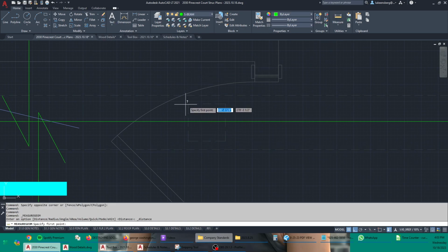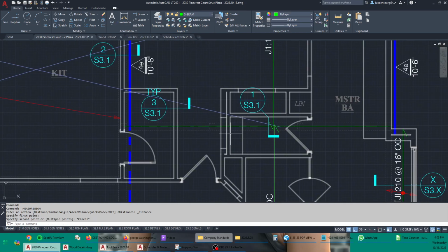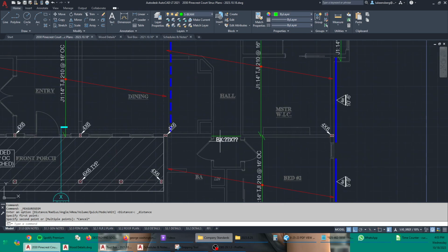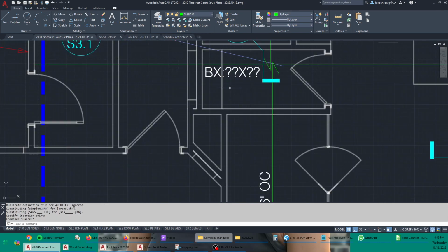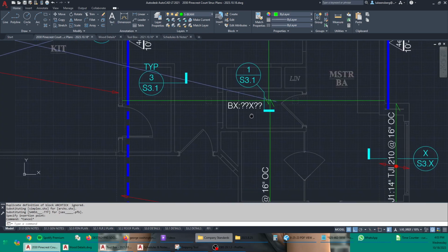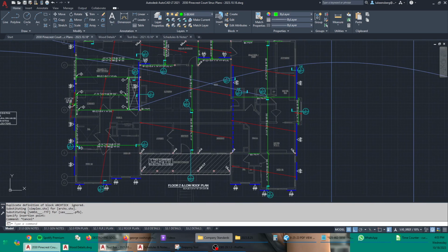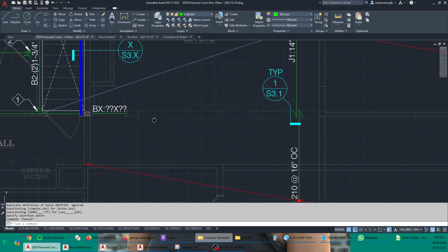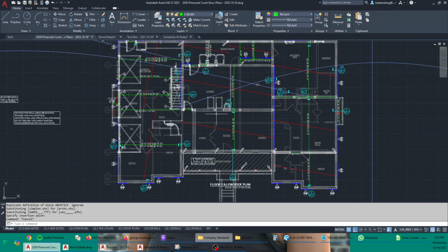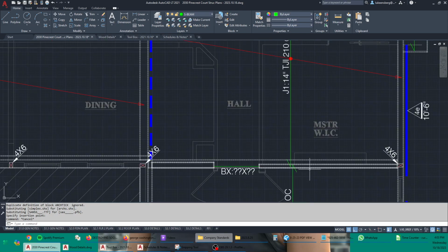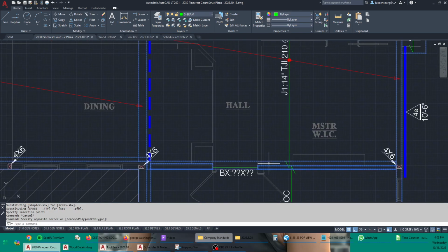The architect has done a pretty good job of thinking this building out. 5.5 by 5.5. So he's seeing these as 6x6 posts, which should be just fine. That should be more than enough capacity. There's my beam label. Question mark means I haven't designed it yet. Looks like we're going to have a similar case over in this area. I'll have to look around for other cases like that. Maybe this one too. Let's go back and look at the architectural section.